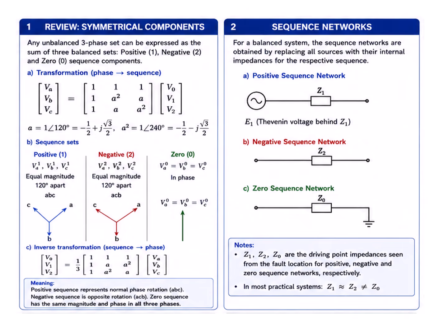Why are these components very important, why are we carrying this out, and how can we employ them? Because we said that we have a positive sequence, negative sequence, and zero sequence, and these will be used for the analysis of asymmetrical fault. So we have to understand the meaning of those components.